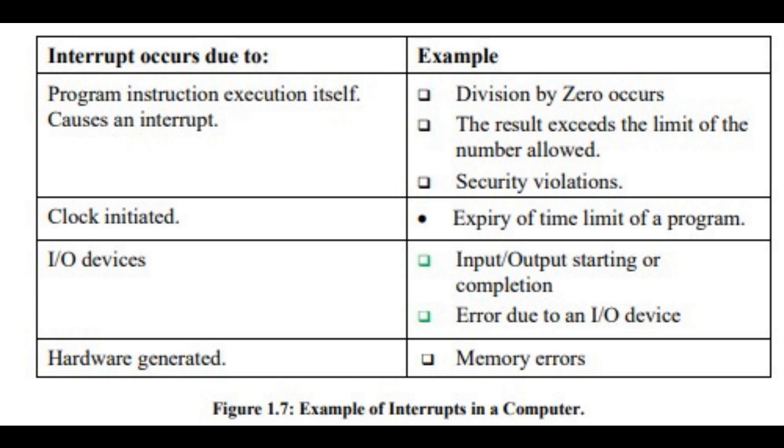The instruction cycle may continue till the time an interrupt occurs. As a result of an interrupt, the CPU knows that some event has occurred and then the CPU stops the execution of the current program and goes on to process that event. The CPU then uses the following steps to process the interrupt. The CPU identifies the source of the interrupt.